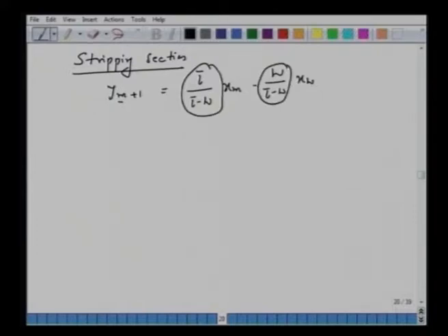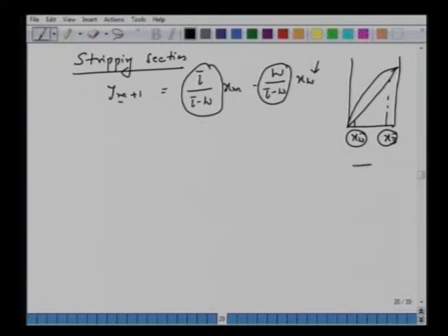The only thing we do not know is this mole fraction xw. So that's what we said in the McCabe-Thiele method. Even if you know the slopes, if you do not know the compositions of the 2 products, you cannot draw this graphically. So neither xt nor xw is known to us. So we are trying to solve analytically, and these equations can always be programmed for every stage. So you have to realize that for all stages above the feed, and all stages underneath where the feed enters, we can write down 2 equations.